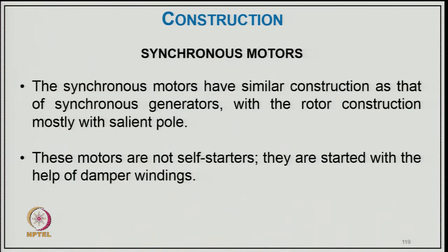Then coming to the construction of the synchronous motor. Synchronous motors typically have a construction similar to that of a synchronous generator, with the rotor mostly of salient pole type, which runs at low speed. Of course, there are also high speed synchronous motors, which are of cylindrical nature. These motors are not self-starting, so they are started with the help of damper winding.